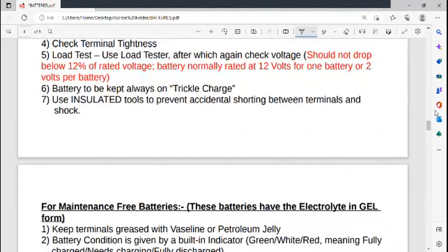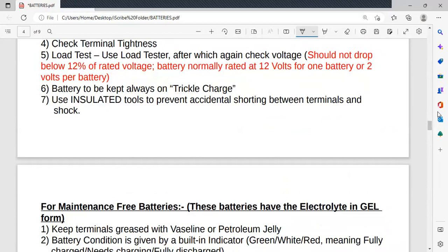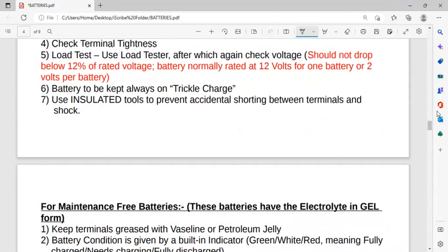The load test. Using a load tester, sometimes they have it on board, but if you do not have this load tester on board, then you should connect all your equipment, as I said, mainly for your GMDSS batteries. Then you switch off your AC, whereby everything switches on automatically to your GMDSS battery source.